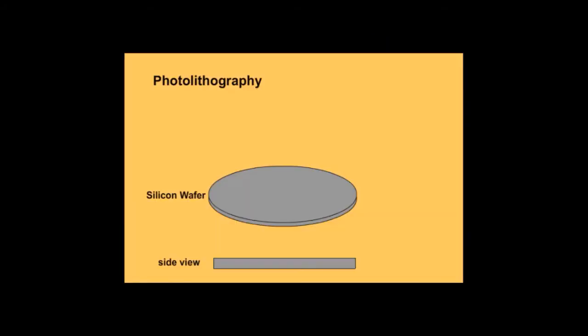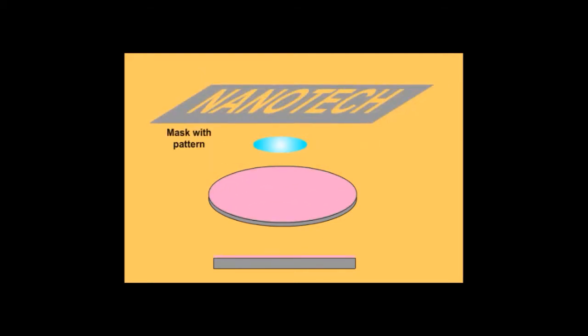Lithography in general is a way of transferring a pattern. We use two different kinds of lithography to transfer patterns of very small size: photolithography and ebeam lithography, or EBL for short. Photolithography uses light to expose a photosensitive resist, similar to exposing silver emulsion in the photographic process. Light shines through a photomask like a transparency, and the pattern of the mask is reduced and transferred to the resist. After a short bath in developer, you can see the pattern in the resist layer.